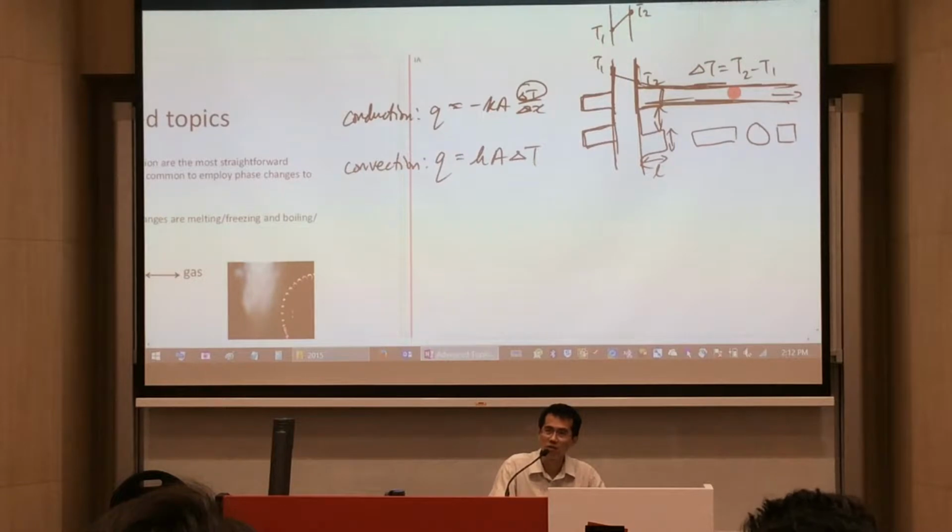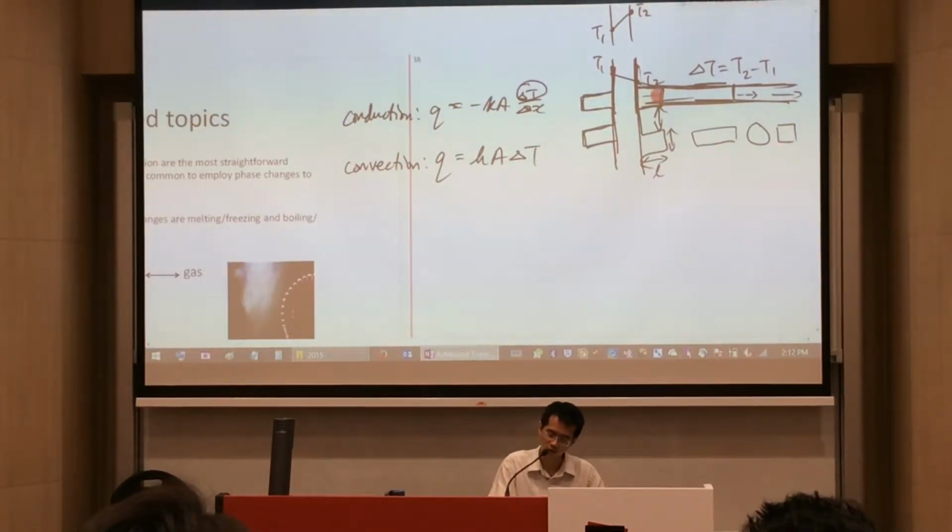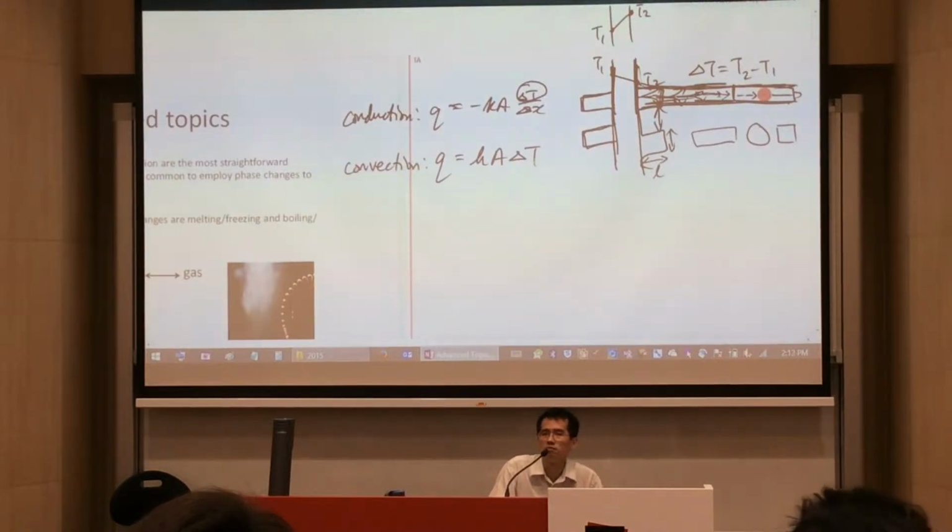Your effectiveness of the fin, and there's a study behind it, there's a certain limited length beyond which going any further doesn't make sense anymore because it's not that effective in transferring heat, because your heat doesn't flow all the way to the end in that way. Your heat will go to the nearest escape route. It will go that way. So as we progress along the length, less and less of the heat is going to end up at the tip. Meaning the more length that you have, the less effective is the fin. So even for that surface area, there's a limit.